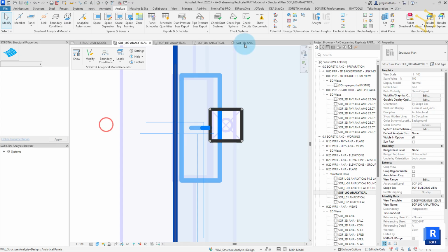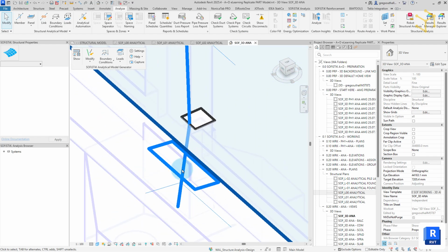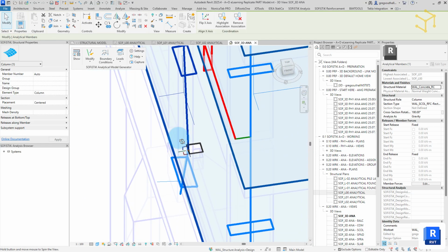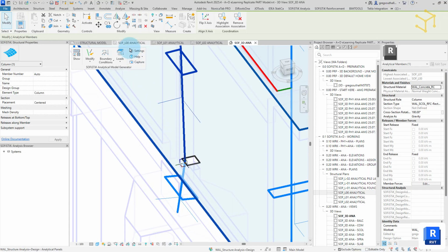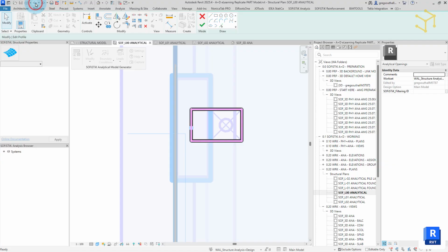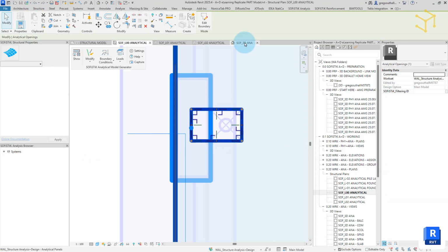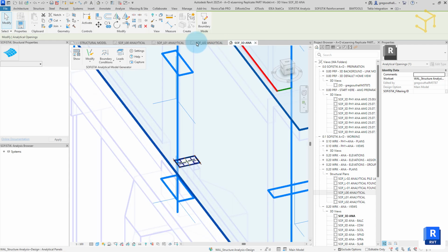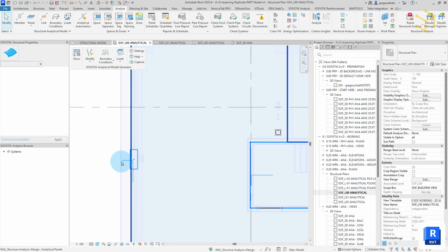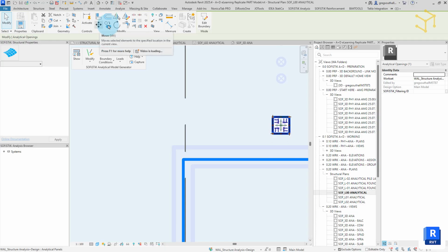As suspected, the amendment affected the position of the intersecting column end node. I'll demonstrate two possible solutions to overcome this issue. Before we do, we'll undo the previous instruction. Both solutions involve deleting the penetration. The first solution is to copy a nearby penetration, place and amend its size.